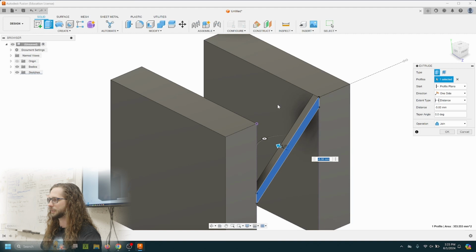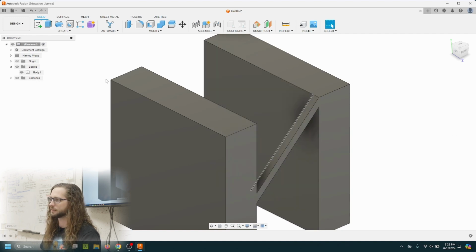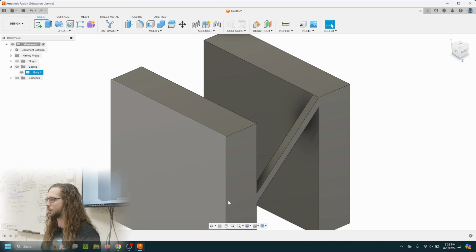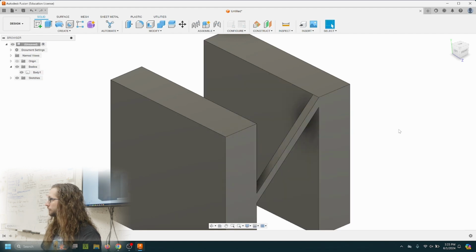That's actually going to connect the transformation to the other parts of the model. So when I hit OK, you'll actually see over here in our tree of things that we've created, before we've done this, we had two bodies, this rectangle and this rectangle. And as I click OK, it's actually going to go to only one, because now this is all one piece.